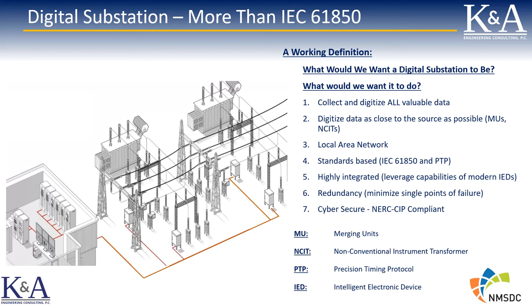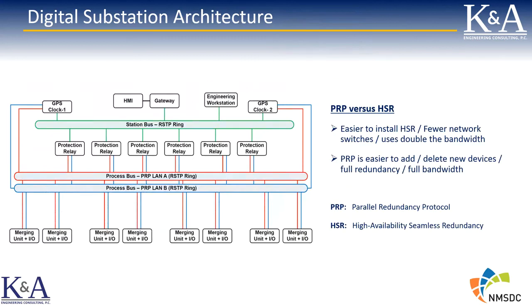Redundancy is important. We're going to show, especially at the process bus level, but overall, we want to minimize single points of failure in the design. And because it's so heavily dependent on networking and software, it's critical that the digital substation also be cyber secure and comply with all the NERC-CIP requirements. Next, please.